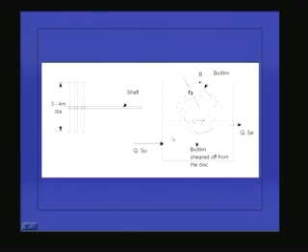But the BOD removal, or the organic matter removal, in this suspended system will be negligible compared to the removal by the attached film. The reason is that we give very little residence time, in the order of 20 to 30 minutes, so the biomass will not get enough time for the removal of organic matter.